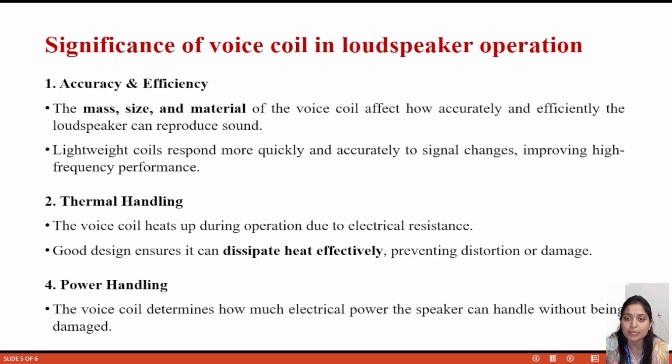The second one is thermal handling. The voice coil heats up during operation due to electrical resistance, because continuous back and forth movement will happen. Good design ensures it can dissipate heat effectively, preventing distortion or damage. And power handling: the voice coil determines how much electrical power the speaker can handle without being damaged. So these are the significant points of the voice coil in making the loudspeaker.